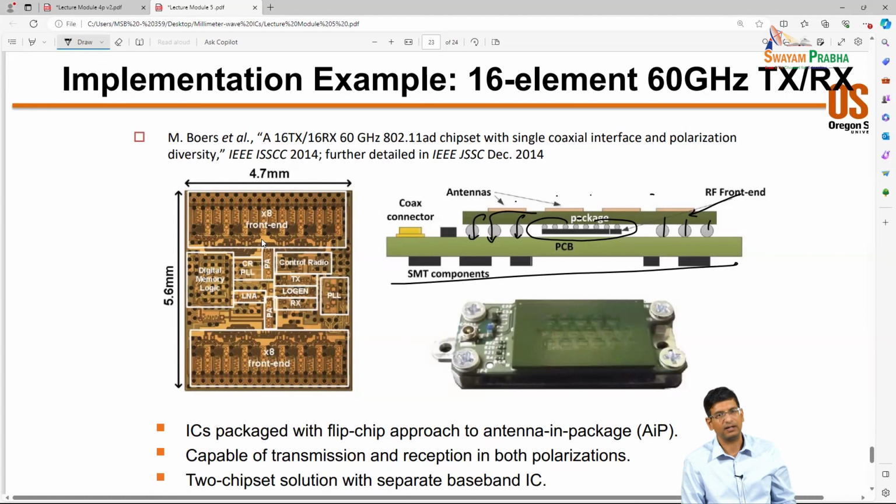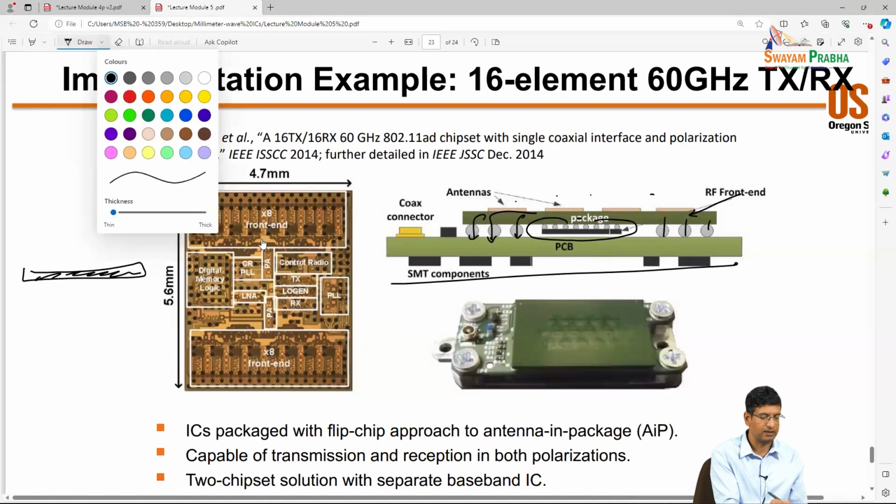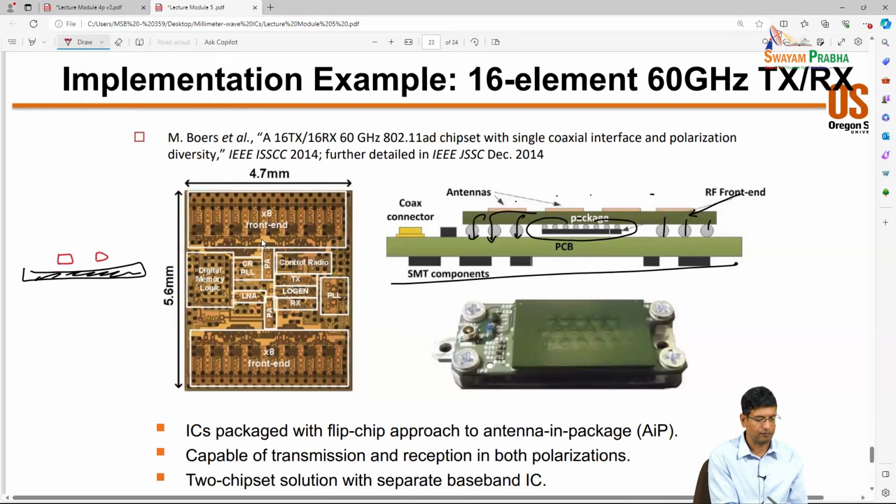But in the 2x2 array that we talked about, the frequencies are low enough that on your PCB itself, you would just have multiple ICs that are directly flip chipped on. And then you would have all the routing, etc., in multiple layers of the PCB. So in that case, you can also imagine that the carrier PCB for that large array is quite complicated and has a lot of layers to accommodate all the RF and power lines that are going through.